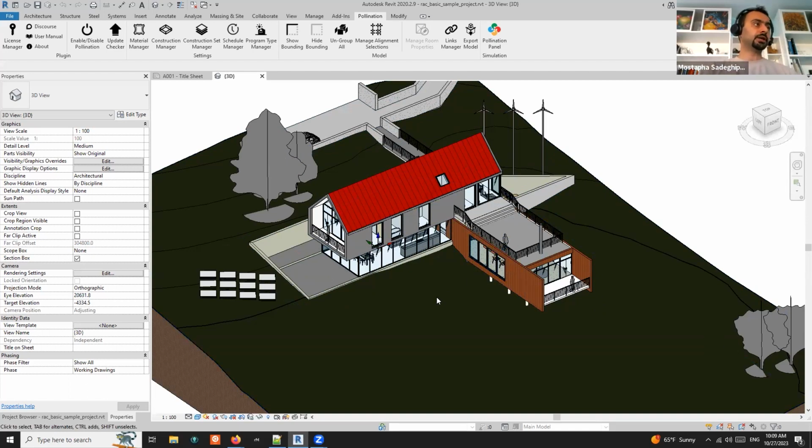So what I'm going to do is export the first floor first, right? And then we talk about different concepts there, and then we move to the second floor. And this is something that I suggest you do for any model, even if it's a small model. I would do floor by floor, level by level, and check and make sure the model makes sense. I have seen people try to just export everything and then clean somewhere else. It won't work well, unless the model is very clean, which almost never happens. You want to make sure you check it level by level. So this is how you would do it.